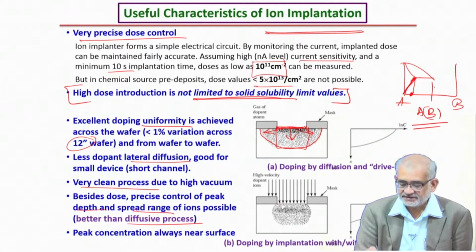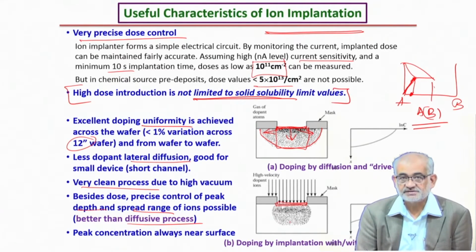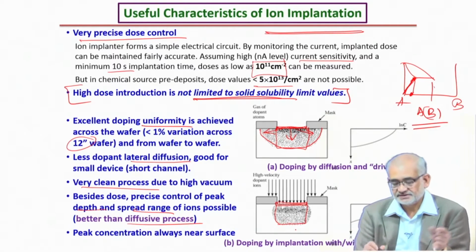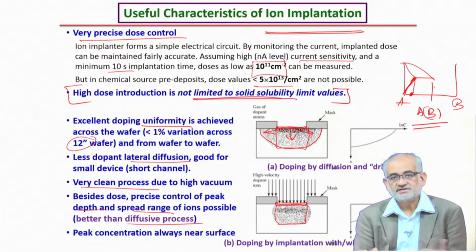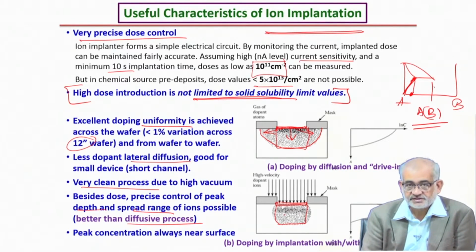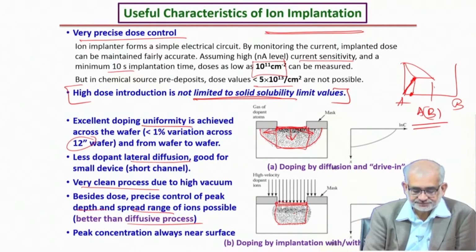In case of ion implantation, which is a directed energy implantation, you initially form a dopant concentration up to a shallow depth, and in subsequent annealing, when you allow the species to diffuse, there will be some amount of lateral diffusion, but generally the profile will be fairly close to the targeted range. So that means the precision of the performance or the properties of the substrate will be better controlled here.